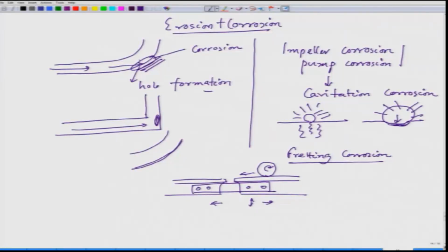When this fretting happens, since they are tightened, there could be a formation of oxides at the interface between the fish plate and the steel of the rail. Because of this fretting action, oxide forms on these two surfaces, and there is a small amplitude vibration under load because the train is running on it. Then these ridges might get dislodged.